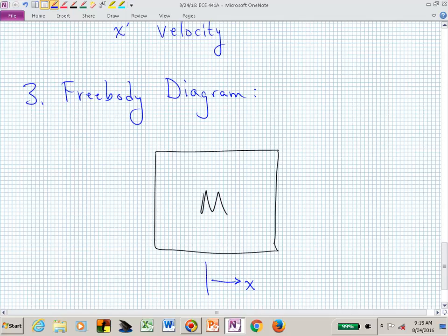We're trying to draw this so that we can very easily just extract the equations that govern the behavior of that system. And the way that I like to do this in a mechanical system is first find my masses, and then all of the position variables that can be independently manipulated. If I fixed, let's say that I had 4 masses, I fix 3 of those and I just concentrate on one of the masses and its free body diagram. I imagine, I do a thought experiment, I just say, let me push that in the direction of my positive x for that mass. And I say, what forces now result from me trying to move that mass in the positive x direction? What sort of impedes that movement?